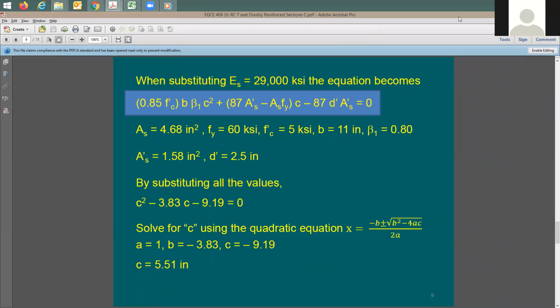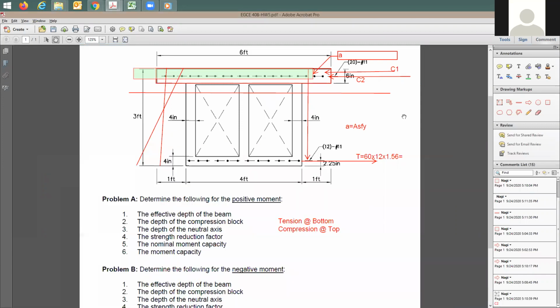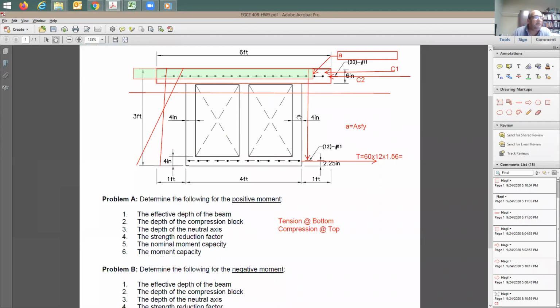Wait, quick question, Professor. Yes. If one of the assumptions is wrong, like the steel yielding for compression or tension, you go back to that formula. Do you still want us to verify that the new assumption is correct? Yeah. So you'd still prove it even after the correct equation? You find out the strain because you need to find out the strain. And this is what I'm saying here: be sure that you have a quick spreadsheet to do this for you. You cannot repeat doing the strain thing here like 100 times. Just do it for yourself.